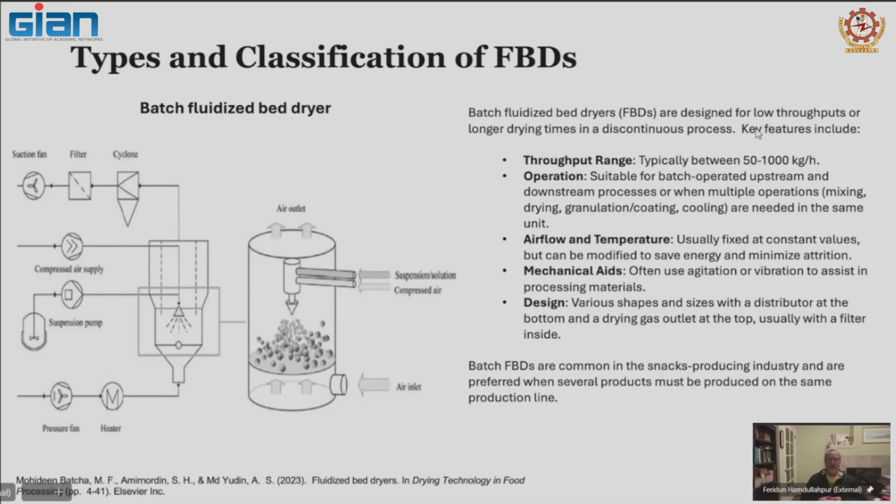With these kinds of batch fluidized bed dryers, even though I say mixing is great, it usually depends on the type of particles. You may not have a well mixed one. We talked about it. You may want to put some mechanical agitators or other means, like a shaker or vibrating bed, and things like that. It's a lot easier to apply those if it's a batch operation.